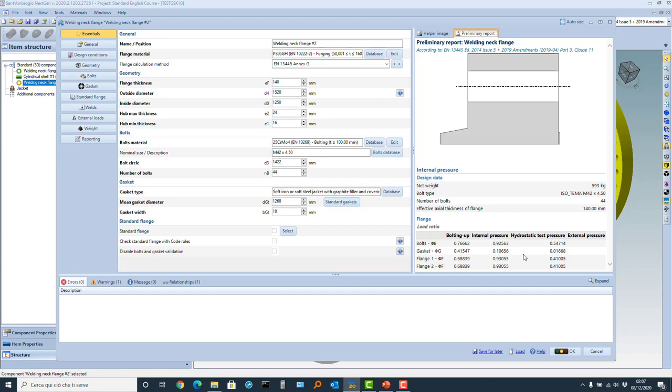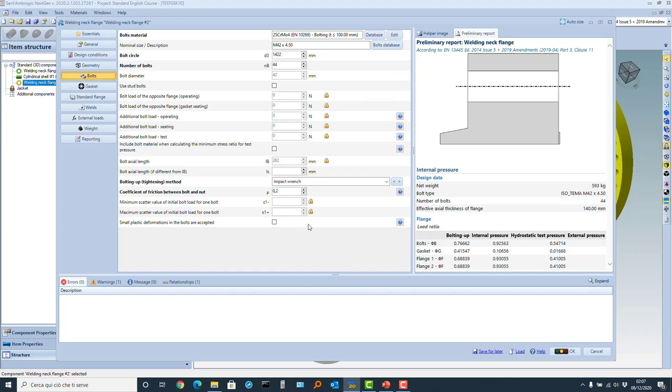One could argue, okay, we have used for the bolts a tightening moment, the tightening device, which is the impact wrench, which is rather, I would say, a rough device, for which the scatter value are possibly high. What happens if we use a torque wrench? With the torque wrench, everything is still okay. There is no big change.